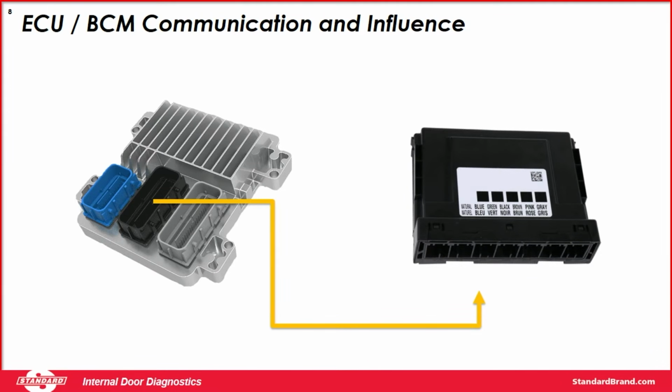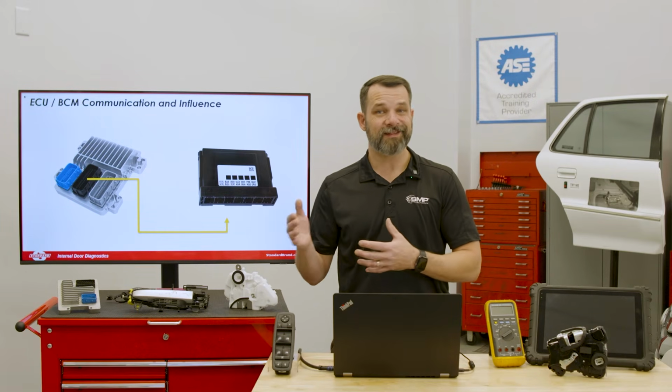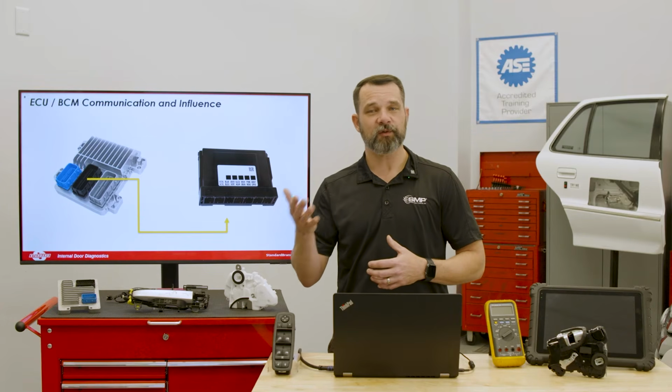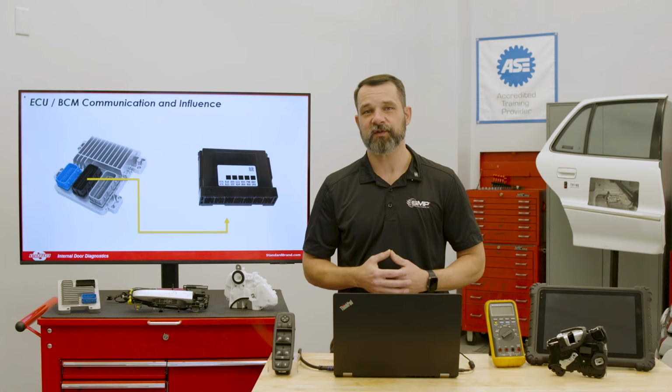And it provides a lot of information that the BCM really needs to make accurate decisions. So some good examples of that ECU influence would be things like the ignition state. The BCM uses ECU ignition data to decide whether the windows should operate. Many modern vehicles disable window functions when the engine is turned off.